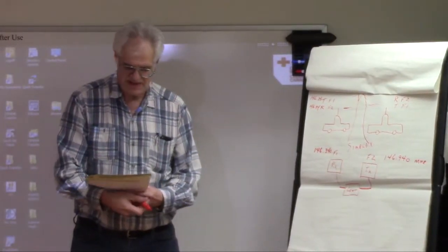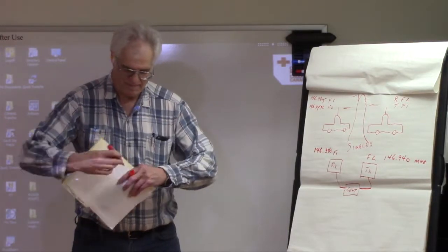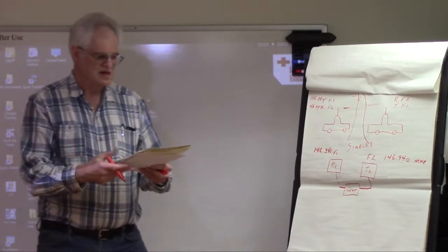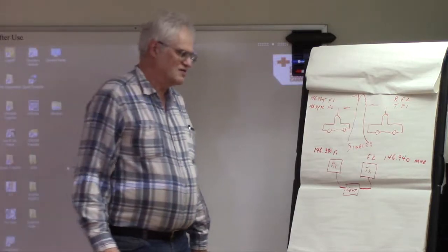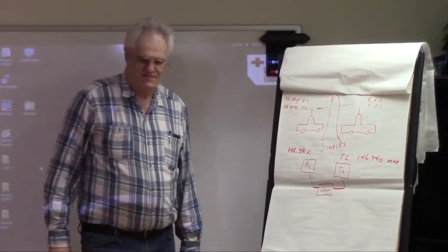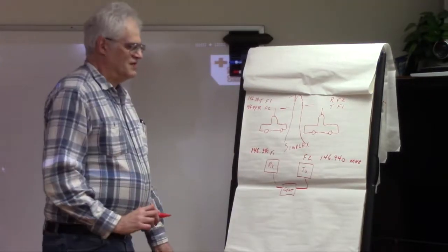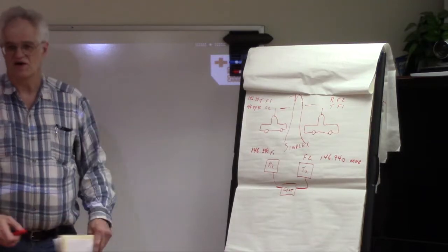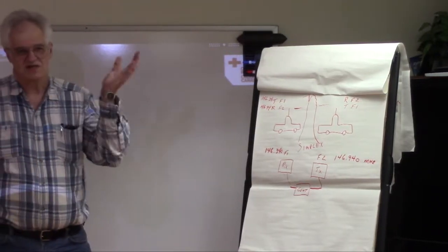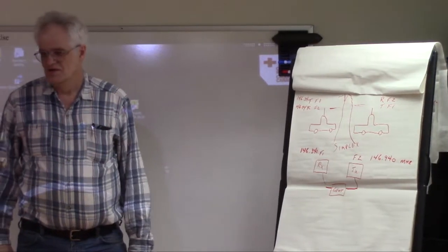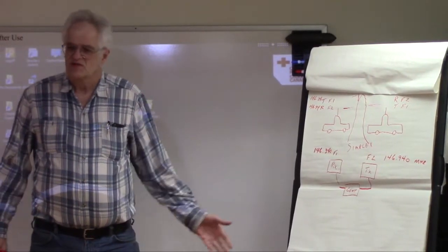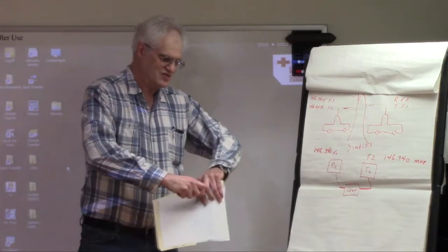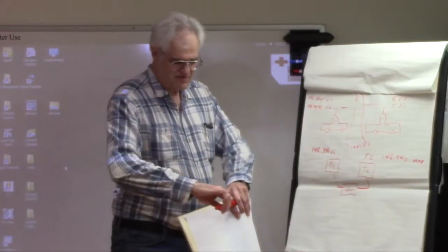Let me just pick a couple of key terms that we come across. Now you'll hear sometimes we talk about, oh, we're putting a tone on the transmitter. What does that normally mean? What it means is, because we had to do that here in the city because you get noise conditions, interference as such, which will actually cause the repeater to be activated spuriously, just on noise or signals that you don't want. So by putting a tone, I hope you remember that from the course.